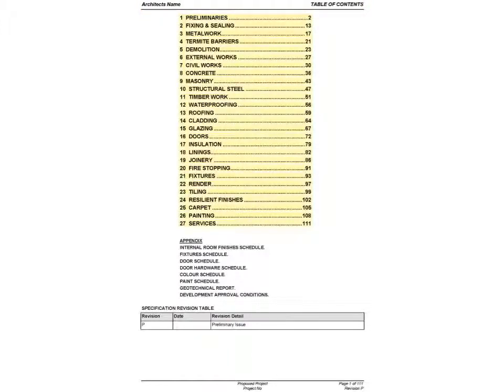Each specification has the same 27 sections. The only time it is less is perhaps for an interiors only project. Having the consistent 27 sections has two advantages. First is project to project familiarity. Second, when a section does not apply to a project, say demolition, that section stays and states simply that the work type is not applicable, enabling contractors to quickly know what is not in a project, avoiding them having to find this out by a process of analysis and deduction.